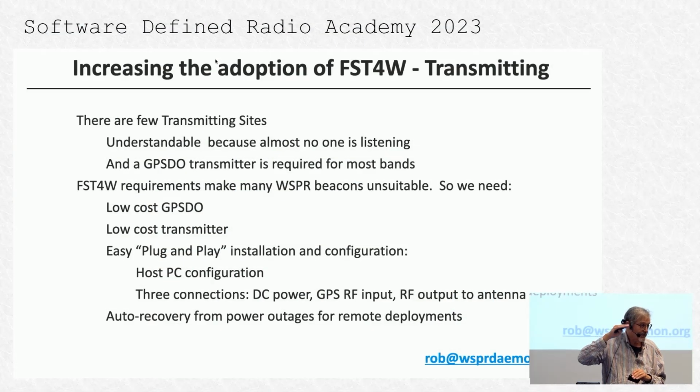So even if you have a strong single hop signal, strong would be 0 dB, when you go into these multi-hop and side scatters, your signal levels are going to drop by 30 dB perhaps, and may be undecodable, even though the signal would in fact be receivable at higher power. So for our purposes, higher power is very helpful for understanding these new propagation modes that we're looking at. So that's a very good thing about the QDX, but like every engineering device, it has its pluses and minuses, its strengths and weaknesses.